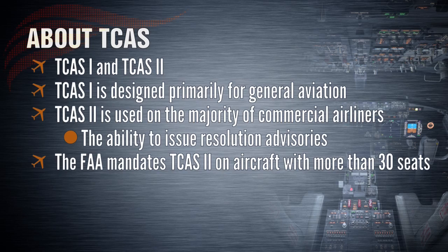Currently operational on most aircraft is TCAS 2 version 7. Version 7.1 has been projected for mandate by EASA on new-build aircraft in March 2012 and for retrofit by December 2015. Version 7.1 introduces improvements designed to overcome weaknesses that failed to avert the 2002 Überlingen disaster in Germany.